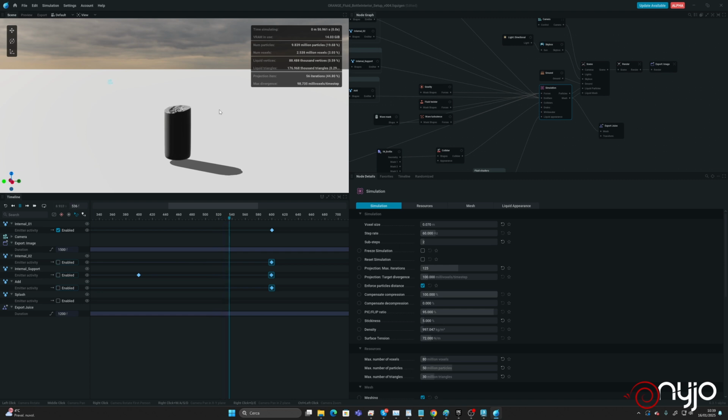So let's wait to have a little bit more frames, and we can go lower with the voxel size because it's just 3% for the moment. So we are going to use less memory. Now it stops, and the fluid should start to stabilize because it is still moving, but you see that it's no more going up.